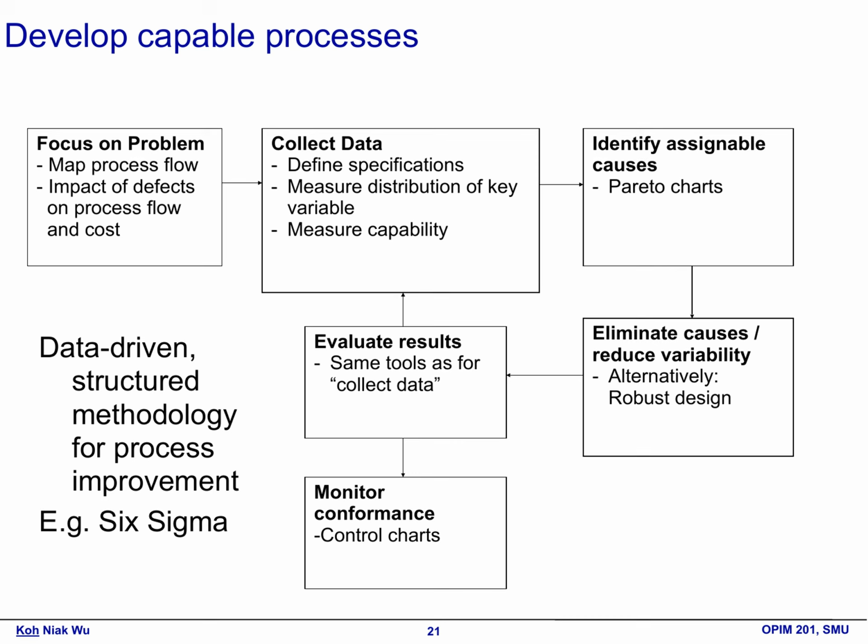Armed with insights into the causes of defects, the team now focuses on eliminating them. They opt for a robust design approach, making necessary adjustments to both processes and equipment. For instance, they implement routine checks and preventive maintenance on the identified machine. Additionally, they redesign certain elements of the process to reduce variability, such as standardizing tool setups and employee training procedures, aiming for a consistent output.